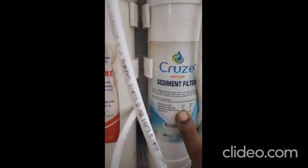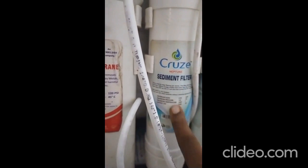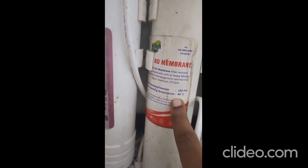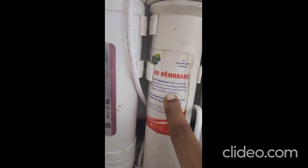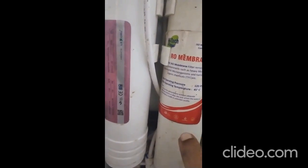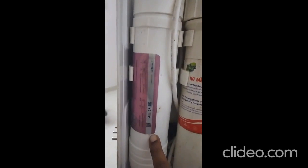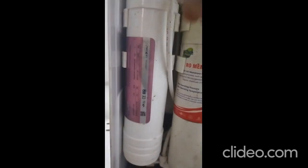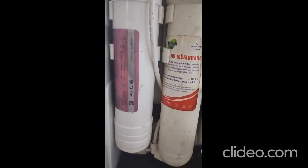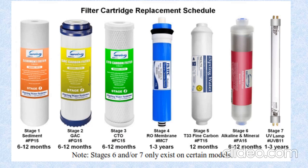As you can see here, all the sediment particles, fine particles are again filtered off, and from here the water goes into the RO membrane, which we have learnt, where the ionic and non-ionic particles are filtered. 99% purification takes place, and then it gets into the post-carbon filter, which is a fine carbon filter to ensure the purity of the water. Filtering any dust particle from the filter so that it should not enter into it.